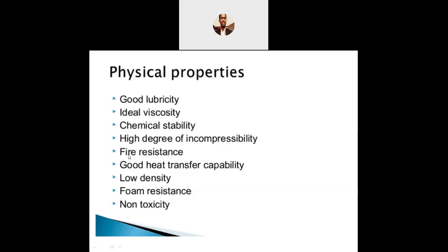It should be fire resistant. This is a point to be noted. If it is not fire resistant, what happens? Because of high friction or high temperature, it may catch fire. So in this regard, we also concentrate on fire and flash point. Okay. Good heat transfer capability, low density, foam resistance, and non-toxicity. It should not be a toxic one. That is what they say.